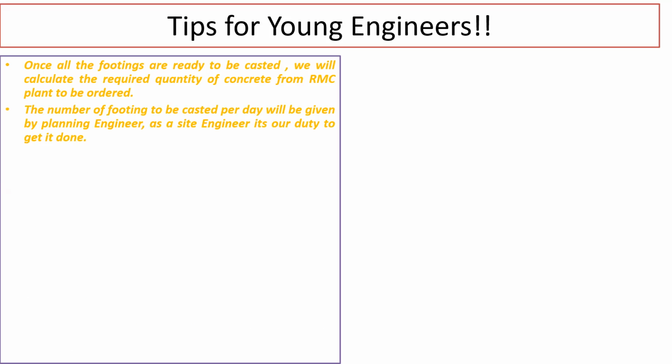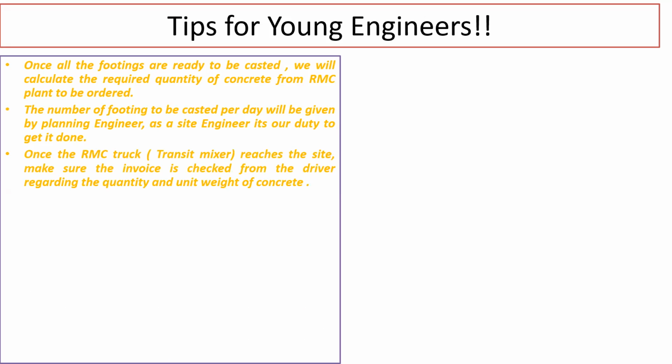So next, the number of footings to be cast per day will be given by a planning engineer, and as a site engineer, it is your duty to get it done, as I already mentioned. Once the RMC truck, that is a transit mixer, reaches the site, make sure the invoice, meaning the bill, is checked from the driver regarding the quantity and unit weight of the concrete. So what is the meaning of this? We'll try to understand this.